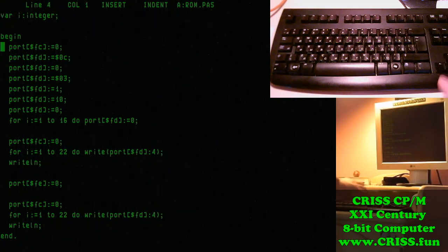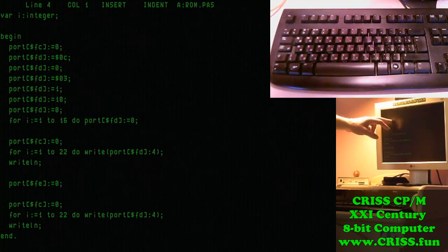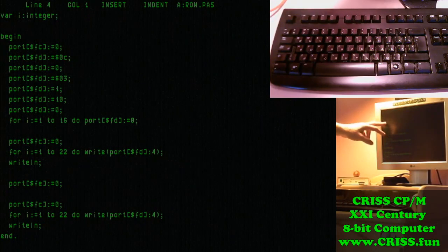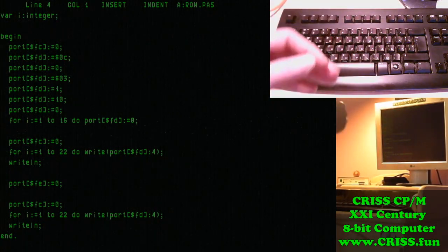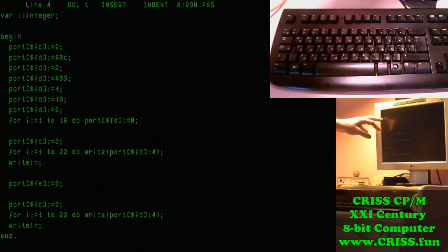Anyone who has read the description of the computer remembers that there are special data blocks, the work with which is based on the same principle. First we go to the port address. Here we have FC, we write the address in this data block. Then everything we write to port FD, we sequentially write or read, no matter what we write or read to the port, the pointer will move by 1 each time.